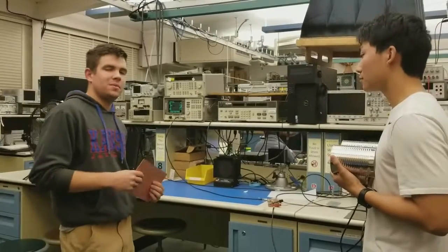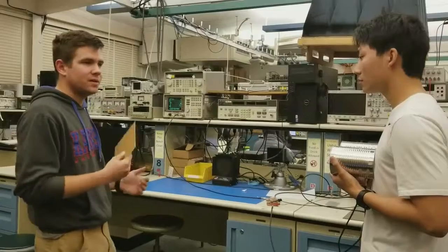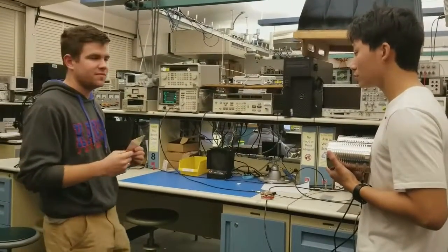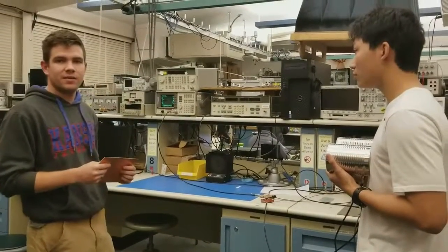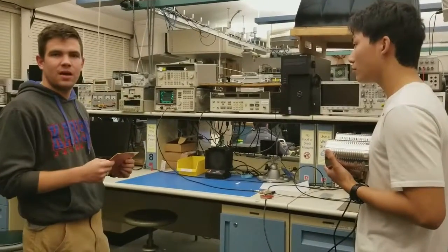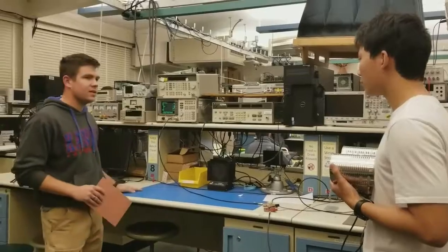So the testing setup we have is the 2 antennas acting as a radar and a moving piece of metal to pick up the sent out frequency, which is picked up by the receiving antenna. The frequency range that we have is 2.35 to 2.36 gigahertz, which gives us a bandwidth of approximately 10 megahertz, which we'll be measuring on the spectrum analyzer.